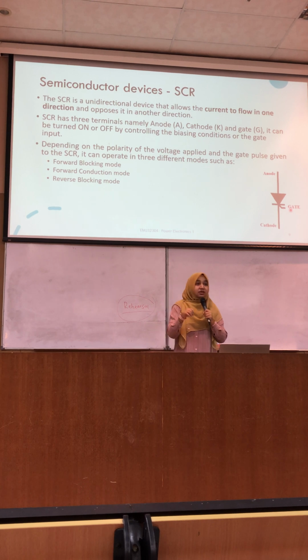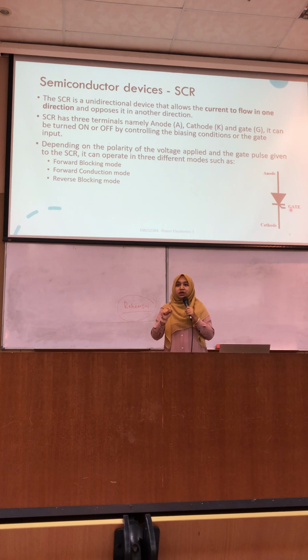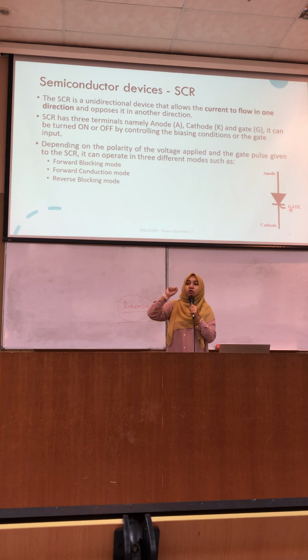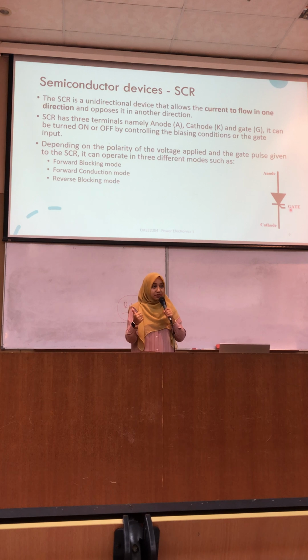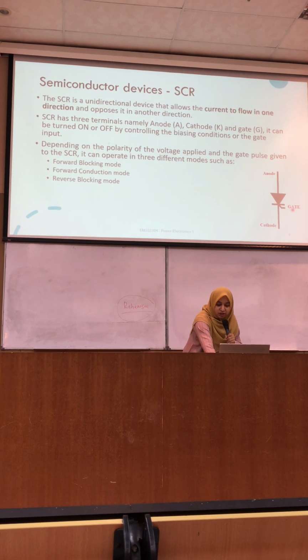So what kind of signal do you need to give in? For this SCR or any other transistor family later, all the gate terminals we are going to give in terms of pulses, 0 1 0 1 pulses. These pulses you can generate from a pulse generator, a clock, or using a microcontroller. The output that we want is pulses, 1 0 1 0. So these pulses will be put into our gating terminal over here.